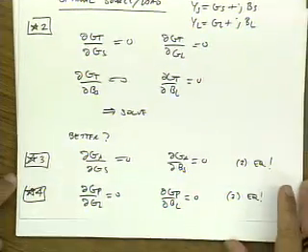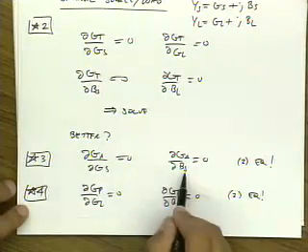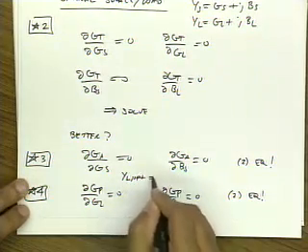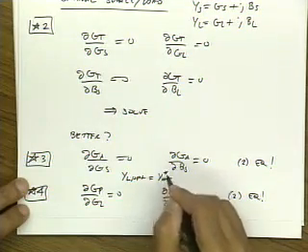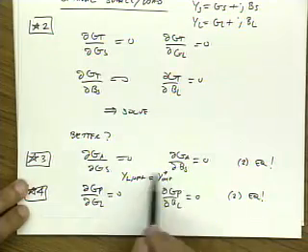And when you're done, so for instance, if I solve for GS opt and BS opt from these two equations, I can find YL opt by simply making YL equal to Y out star. And Y out, remember, is a function of YS. And so this is a recipe for finding the optimal load.